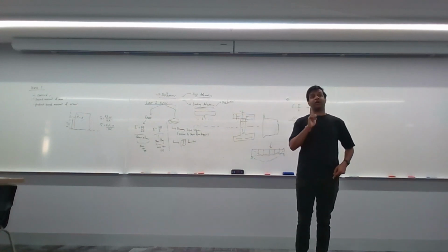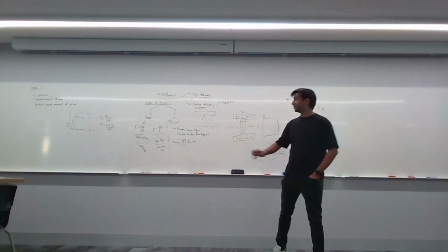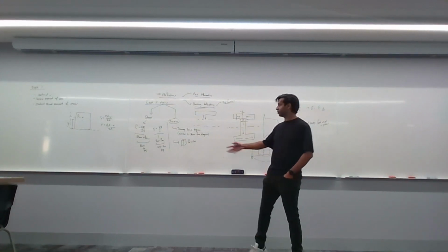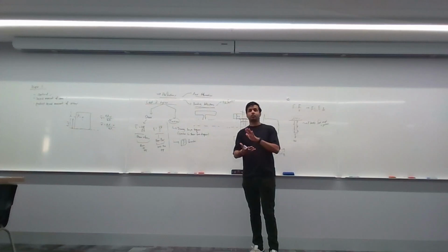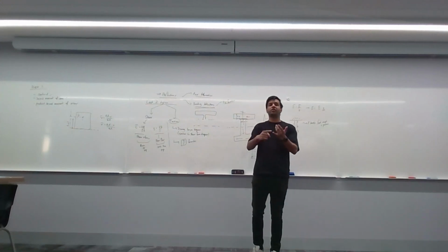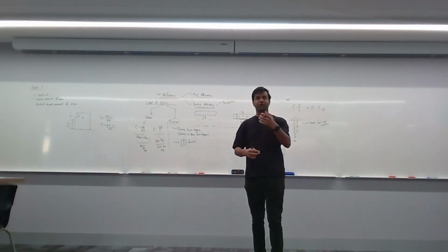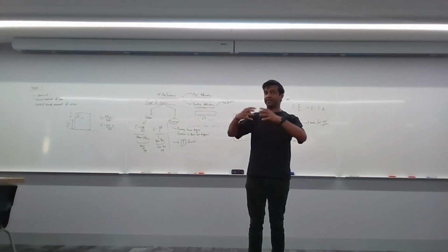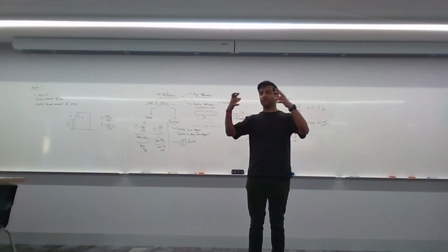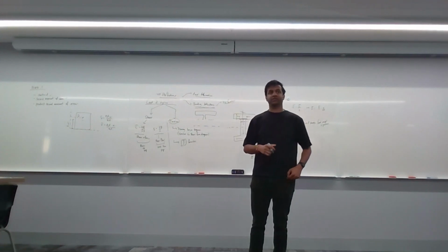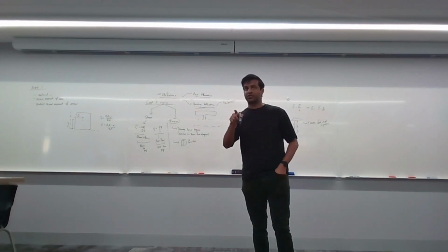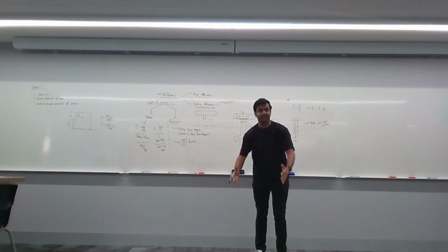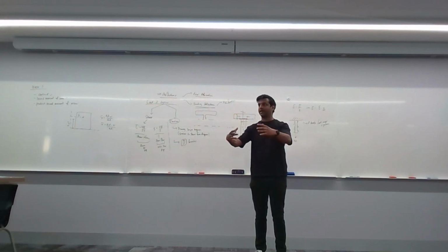Now, the one thing that I do have to note is a possible way of asking these kinds of questions for torsion is by linking torsion. Well, remember, what do you get from torsion? When you apply torque to it, you get shear stresses, right? You get shear stresses at the extreme outer ends of your cross section. If you apply a normal stress also, so say for example, I have a pillar or like a bollard sticking out of the ground, it's circular, right?